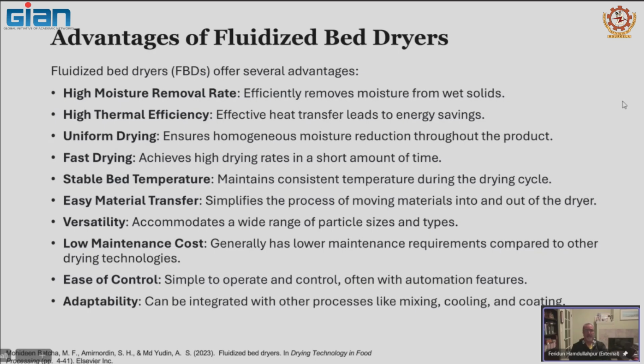First one is high moisture removal rate. It efficiently removes moisture. We talked about this. High thermal efficiency. Remember, for the air you're putting into the fluidized bed, you have to spend energy, you have to spend money to heat this air.